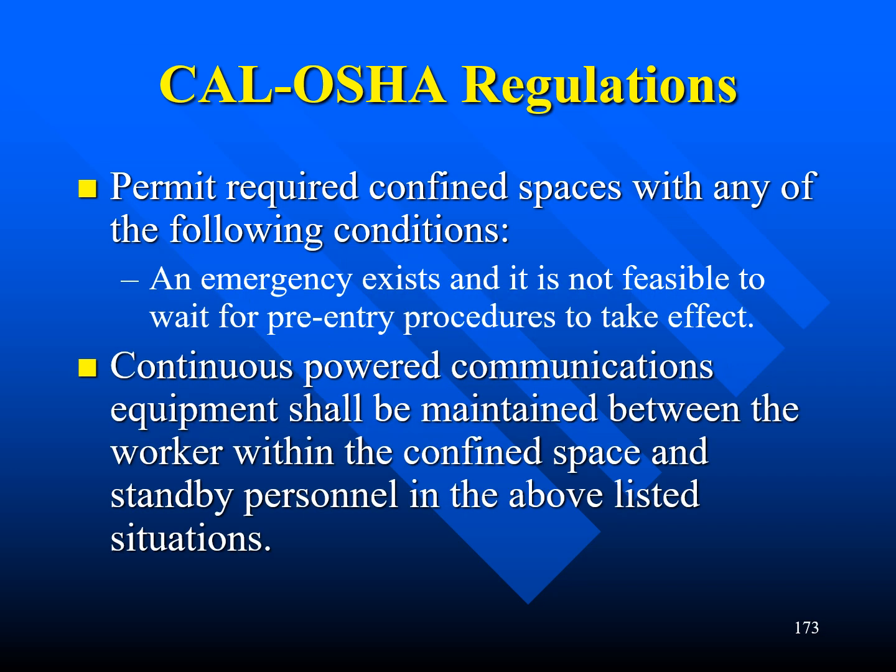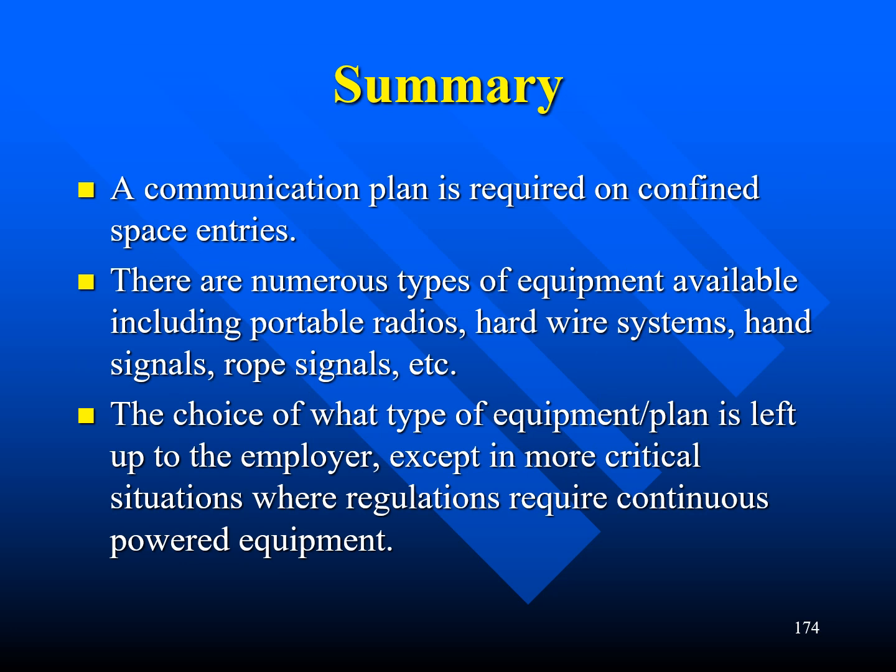Or an emergency exists and it is not feasible to wait for pre-entry procedures to take effect. Continuous powered communications equipment shall be maintained between the worker within the confined space and standby personnel in the above listed situations. Let's summarize this lesson.